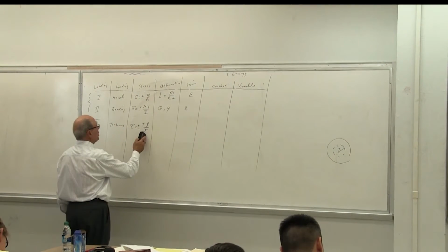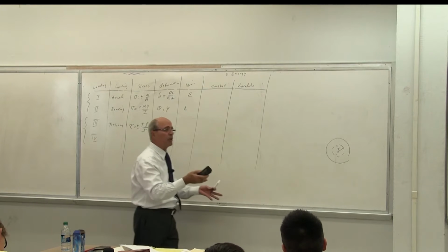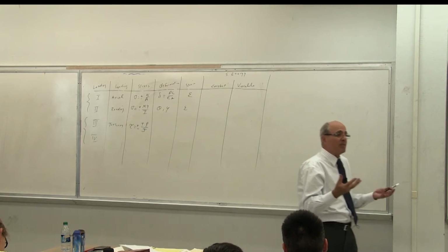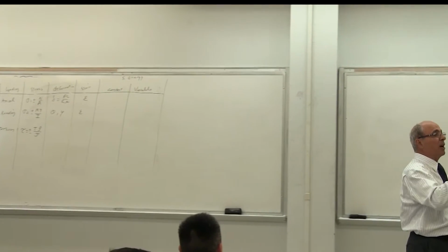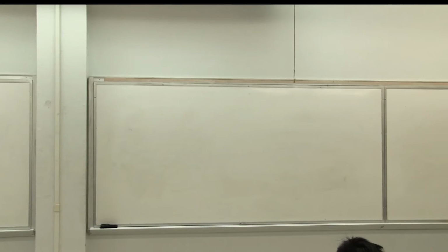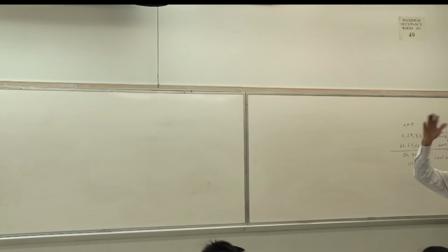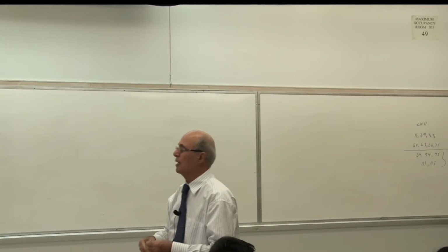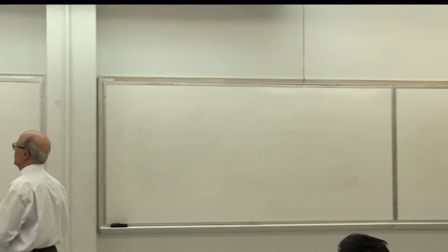Nevertheless, I'm talking about not the outside only. You are using the outside because as a designer you're interested in finding the highest value, but in general, that's the format of a stress. In the beam, top with compression, bottom with tension, it has a linear format that we all went through in ME280. Anyway, I don't have to mention that.